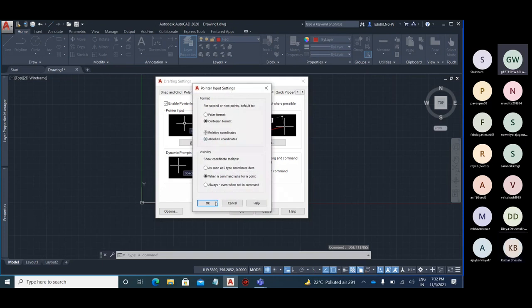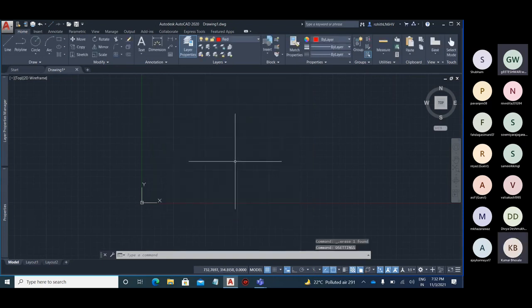If we have to insert the CAD file in Revit, is it required to have the drawing in UCS or WCS in each format? No, it is not a compulsion. The coordinate system is for Revit's working to understand the thing. You can insert in Revit at whichever point you think is perfect. You can give that as an origin and insert it in Revit.